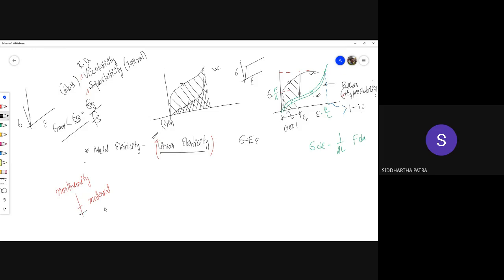Next comes geometric nonlinearity. We have already discussed what is meant by geometric nonlinearity, the purpose of Green's strain. If you really think about it, a beam bends on applying load quite a bit, much more compared to how the load would affect it in its axial direction. A 100 Newton load would affect very little in the axial direction of a beam, but it might cause substantial deformation in the lateral direction.